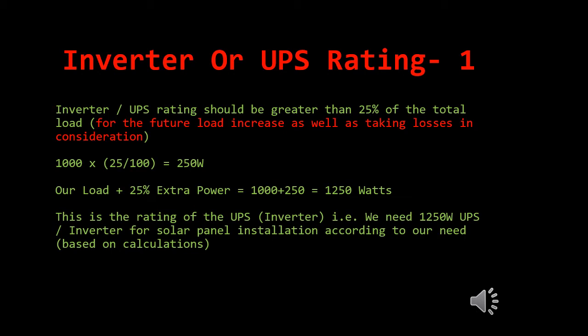Now here we are to calculate our inverter/UPS rating. Inverter/UPS rating should be greater than 25% of the load for the future load increase, as well as taking loss in consideration.